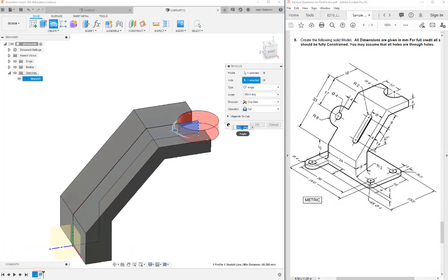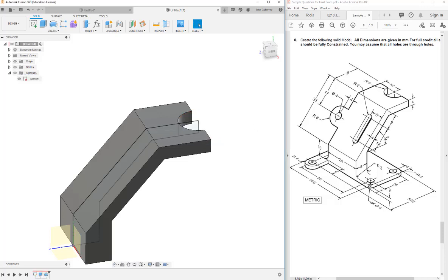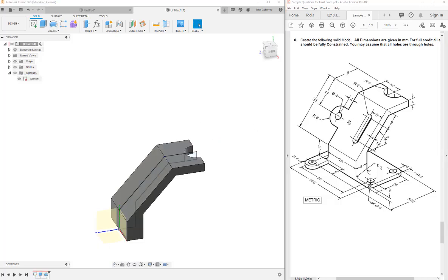And so that's going to make it nice and easy for me. Actually, the hole tool in Fusion doesn't allow you to do a partial drill. It likes to be drilling the entire hole. So this would be an error anyways if we tried to use the hole tool. So I'm going to go ahead and use that as an extrude cut revolve to get that feature right there. So that was something I can capture in that same sketch. So that's always nice. Okay, and so the next thing that we're going to work on is this profile here.